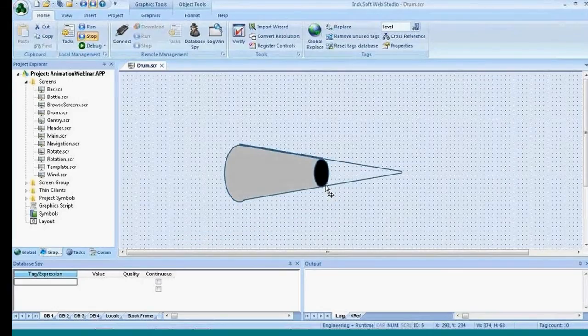I'm close here, but I just scaled this line, or changed the size of this line, until those intersected, and that gives me some help. Let me move this lower one out of the way, and I'll move this upper one up here. Now what this does is give me the rotation point. Even though this line is not the same length, I'm going to rotate around this point where they coincide out here in space.